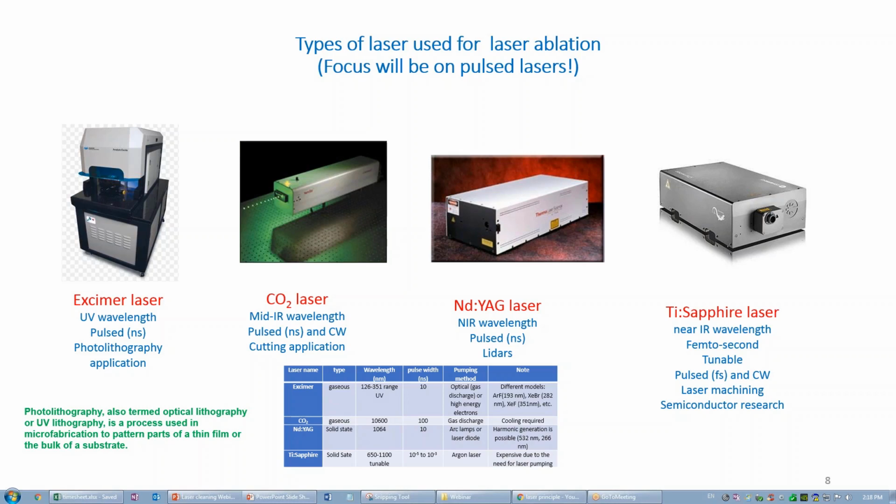And this CO2 laser is quite useful because it's heavily absorbed by polymers and plastics, but not absorbed that well by metals. It's 90% reflective. But there are disadvantages to using this laser because fiber optics are not as available for the far infrared as they are in the near infrared, and they're also expensive.